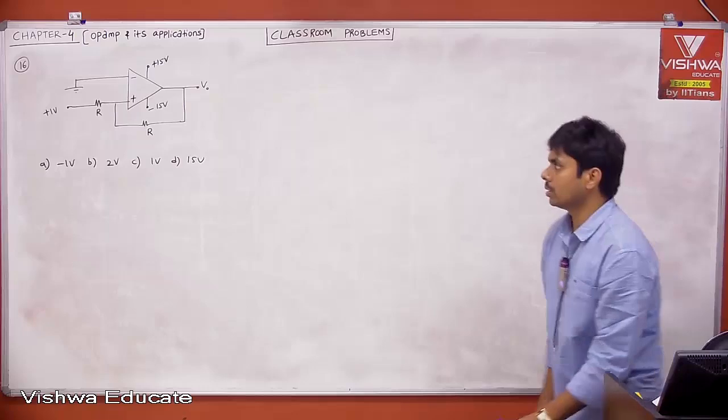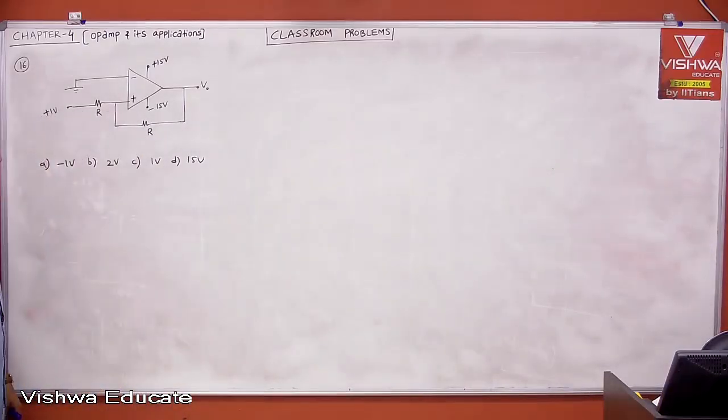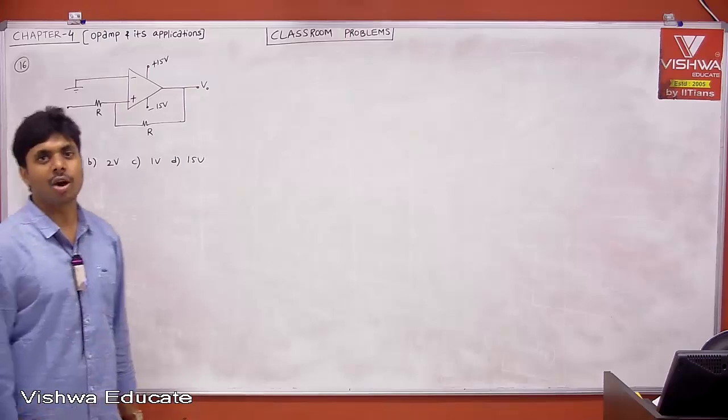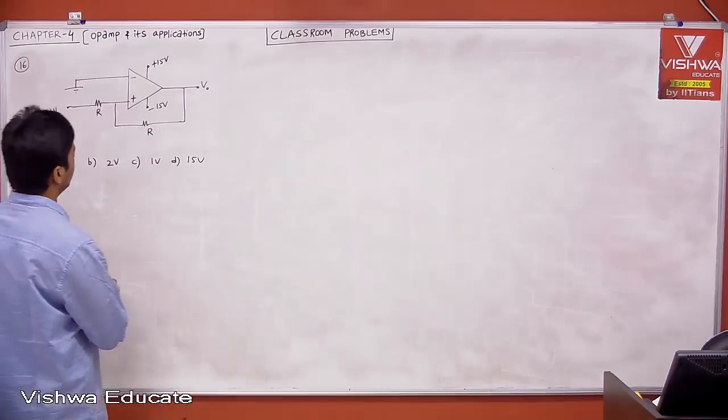Now listen, tell me, negative feedback or positive feedback? Positive feedback, not negative feedback. Remember, if you assume that this is negative feedback and apply the virtual ground concept, then if you do nodal analysis, you'll get an answer, and that answer will be there in the options. Therefore, remember, this is a positive feedback problem.